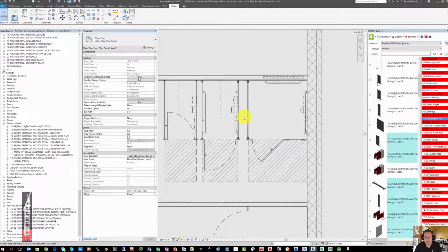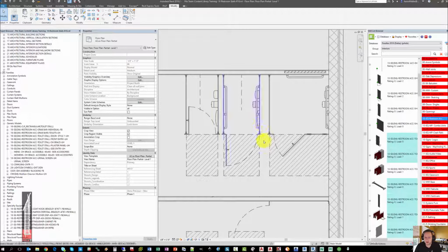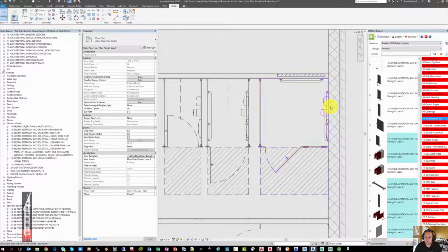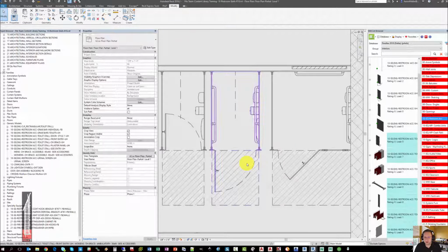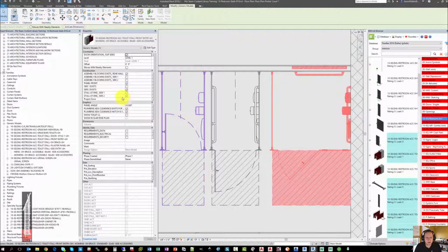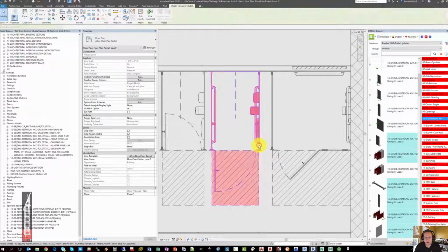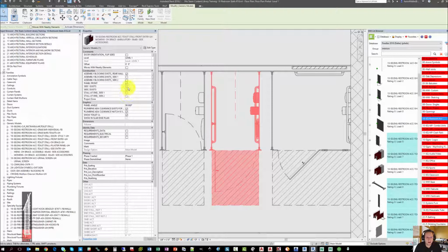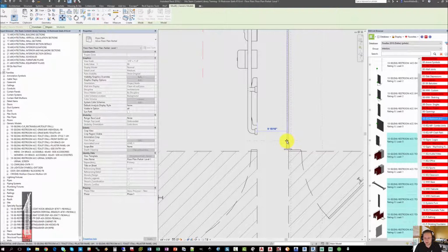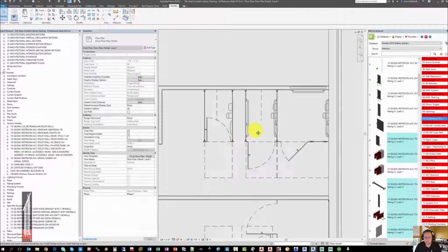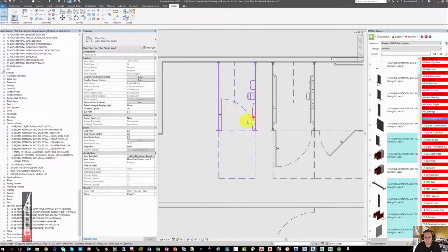Now, we can use all these same options to go through and configure the other stalls. Similar to what you saw us do with the first stall that was overlapping the wall, you can see that when we slide the ambulatory stall into the correct position, there will be overlapping panels and pieces. So what we're going to do here is this stall is not going to be at the end of the run, so that will change the front pilaster. And this stall is neither at the end of either run, and we're going to say side 1 doesn't exist. Now you'll see you have basically just the accessories, and we will slide this stall into the correct position alongside the other one. We will do the same thing for the next stall.